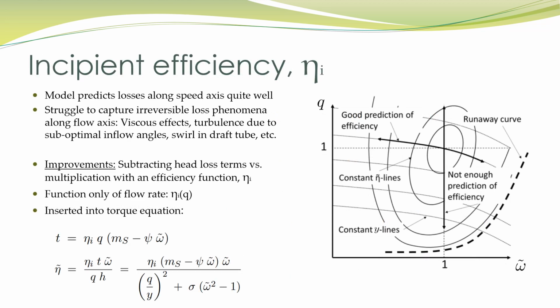So it has been demonstrated in previous works how this model captures different losses, how well it can predict the turbine efficiency. And a really nice way to present the turbine efficiency is in the hill diagram, the hill chart, where you have flow on one axis and speed on the other, and you are plotting lines of constant opening degree together with curves of constant efficiency, where these curves form a hill towards the point of best efficiency, which is here where the red dot is now.